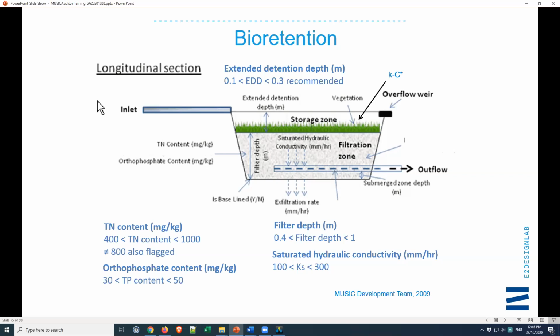So you'll be able to meet that requirement, but also meeting the 65% phosphorus reduction. You'll find if you leave that at 55 or certainly at 80, that you'll struggle to meet that with a bioretention in some cases. So we're being conservative, but we're being unnecessarily and probably overly conservative, leaving that so high. So these are the ranges that we'll be checking.